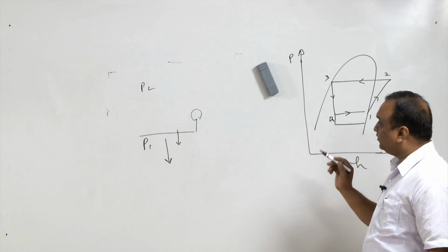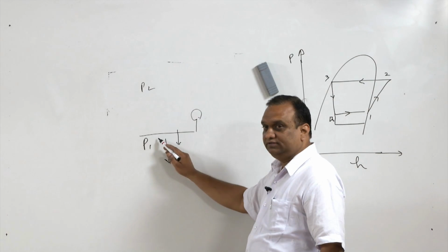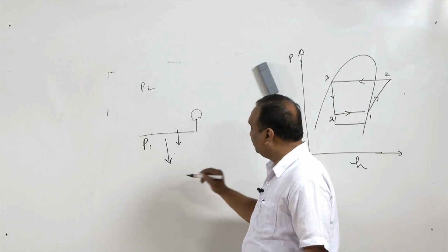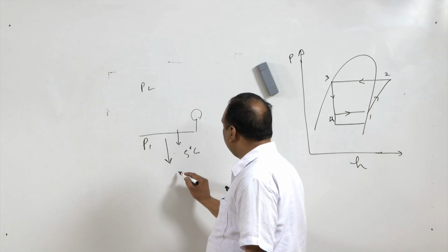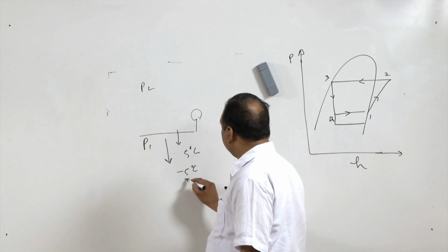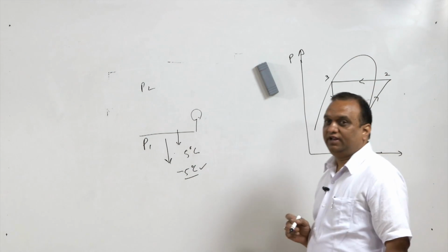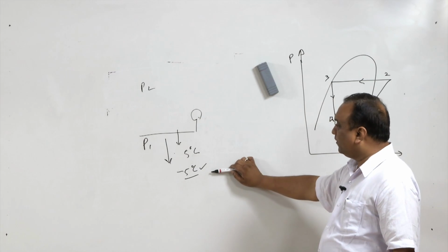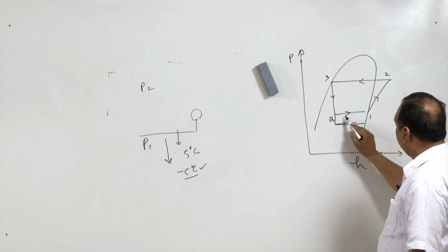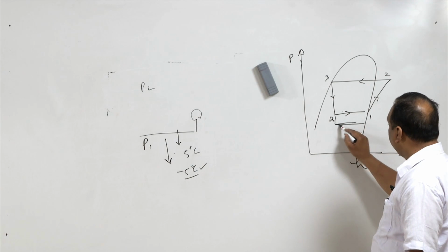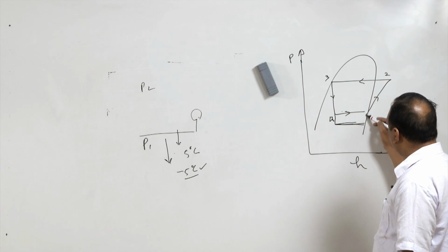And it is misleading, because here on the coils you will be getting temperature, suppose actual temperature is 5 degrees centigrade, in coil you will be getting minus 5 degrees centigrade, right. It is misleading. It appears that the cooling capacity has increased, though the temperature has reduced, but in this case cooling capacity has also reduced.